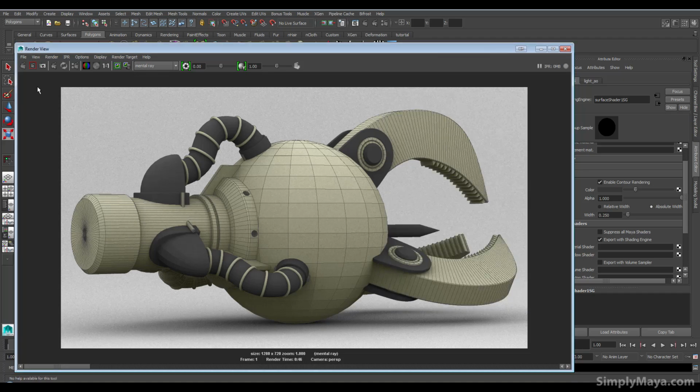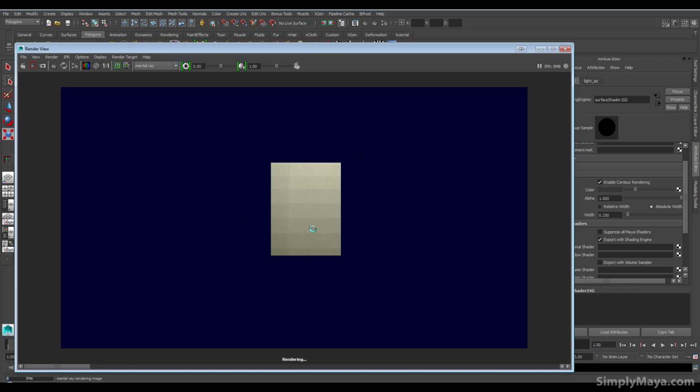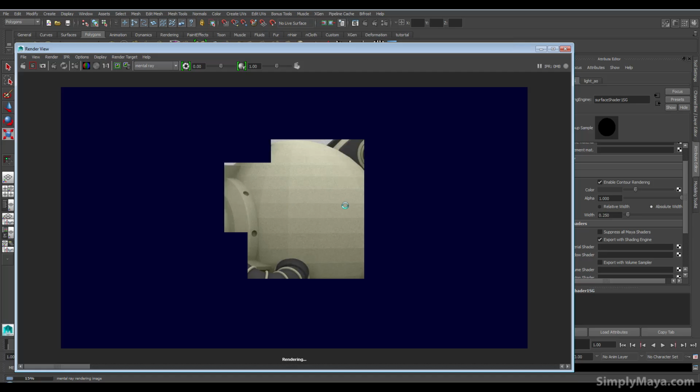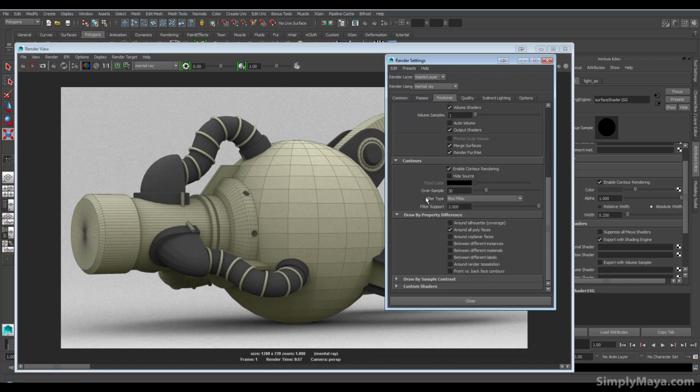So I'll snapshot this. I'll do one last render for this process with this oversampling set much higher, so from 2 to 30, and you'll be able to judge for yourself when I flick backwards and forwards. Okay, so here's the new one with the filter turned up, which has made our lines blurrier, not so jagged, and with that oversampling, it's made more detail appear on these small wires here. So, again, it's entirely up to you, and actually it took around an extra 10, 11 seconds to do all the oversampling, so it's really not that bad.